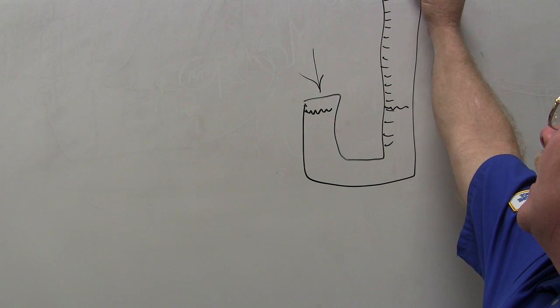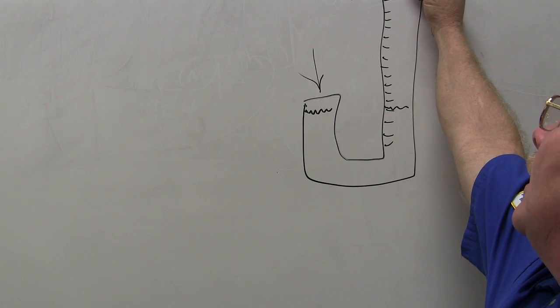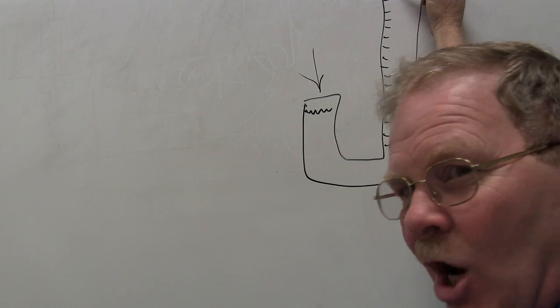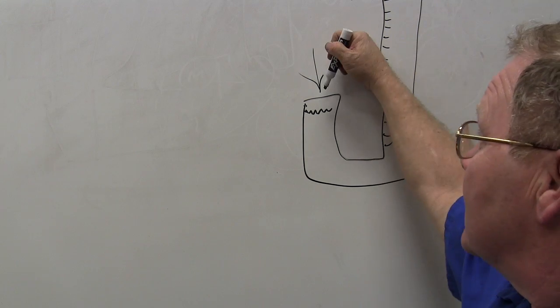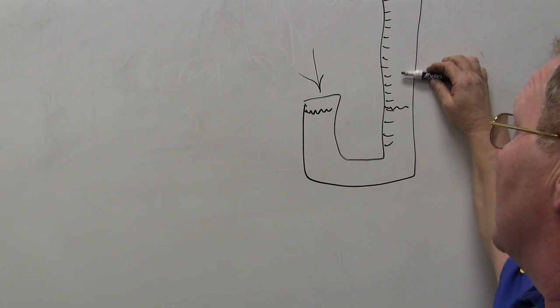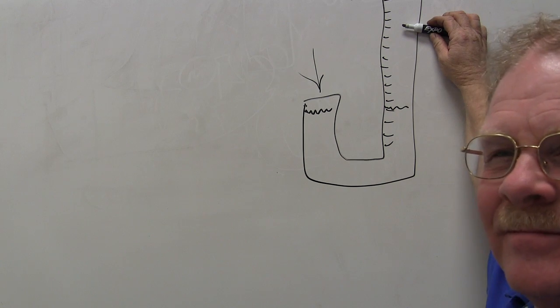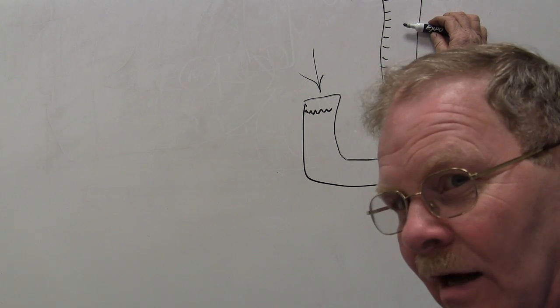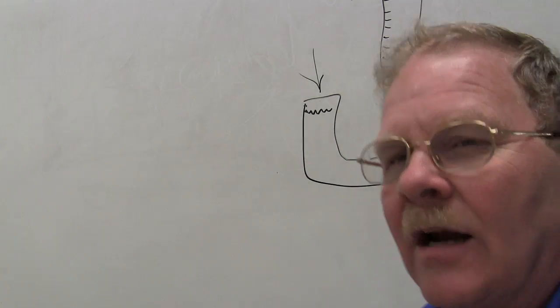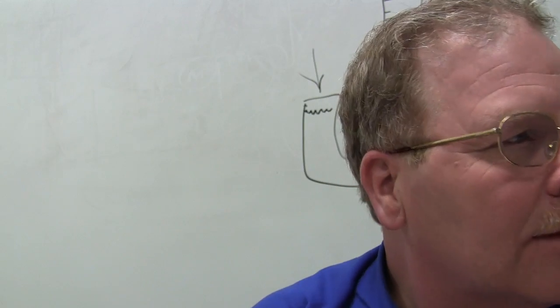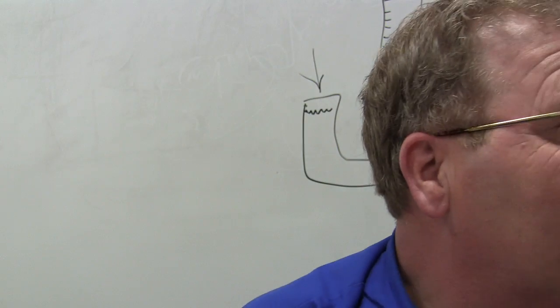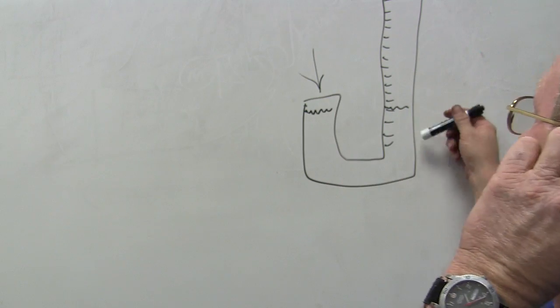Well, you cap that off, and you pump every last bit of the air out of this side while this side remains open. This goes up 30 inches. Now you know, right? That's why you cannot have more vacuum than 30 inches of mercury. That clear? Everybody got that? That's how that was done.